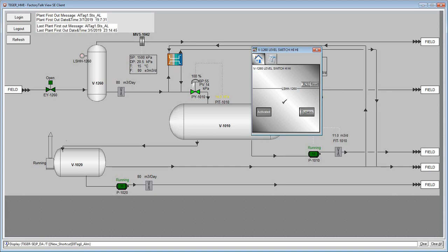So you have the home tab, which is designed for the user, and then the settings tab, which is designed for the admin or the developer. So for example, in this particular case, for the discrete alarm, you can see the status here, it's good. The other thing that you can see, if you point to that status, you will see the in alarm and the last time it has been acknowledged, and actually that time is coming from the PLC, so the alarm is time stamped in the PLC in this case.